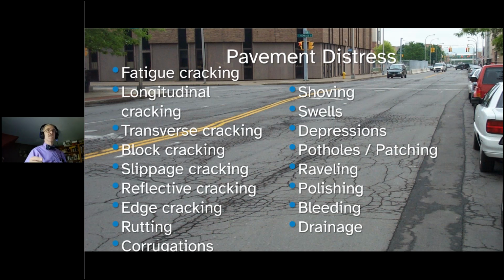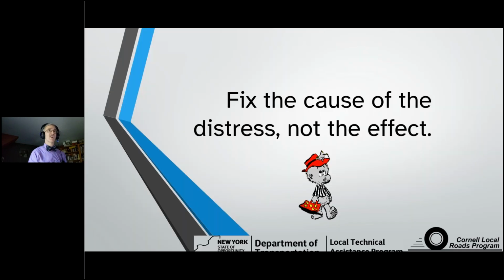Look at the distresses and let them tell you what the repair should be. You might have to do a test pit to look underneath, but at the end of the day, you need to fix the cause of the distress, not the effect. What's causing the distress?